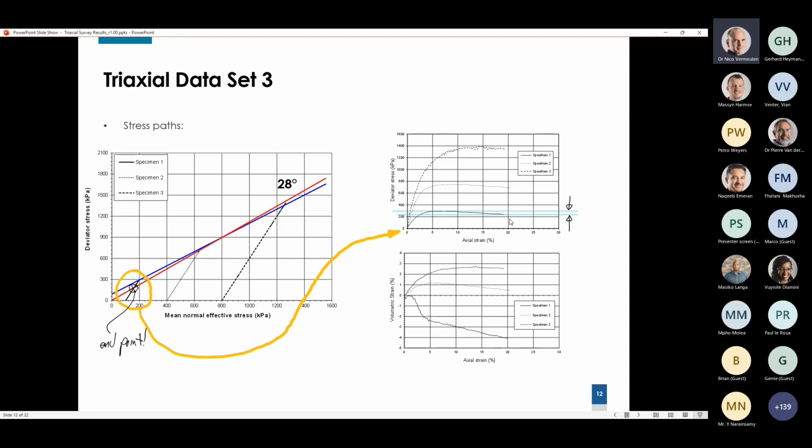So in actual fact, if we had to trace the stress path on the left here, we will start at the bottom, we will rise at that slope, carry on up to the blue line, then that's the peak. Then as we keep on straining it, it will come down that same slope and end up probably close to the little X marks the spot sign there.